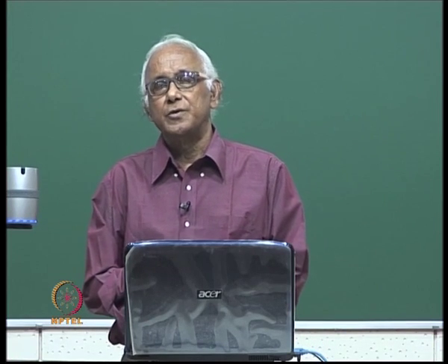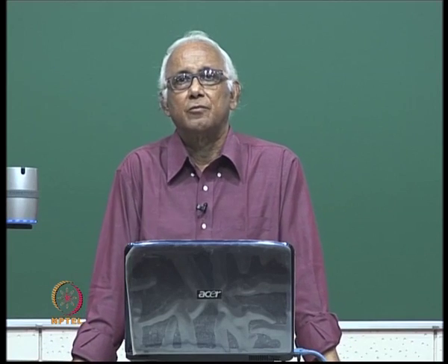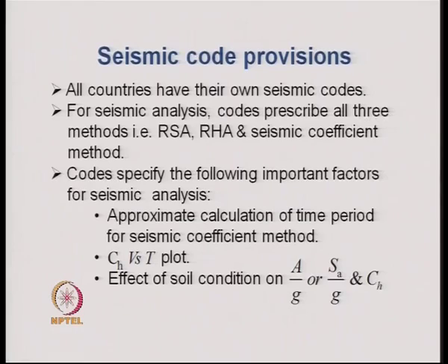The seismic coefficient method as such has certain limitations, in the sense that it does not take into account the participation of all modes of the structure in the response. Secondly, it is based to some extent on empirical formulas which are difficult to support completely theoretically.